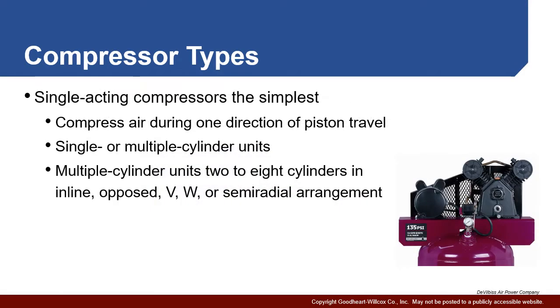Within our reciprocating compressors, we have what is known as single acting compressors and double acting compressors. Let's start with single acting. They're very simple. You see an example here on the right, and essentially why they're considered single acting is they're very much like a single acting cylinder in that they only work in one direction. So essentially, as the piston extends, it compresses that fluid. As it retracts, it pulls in more air, but it doesn't generate any compressed fluid.